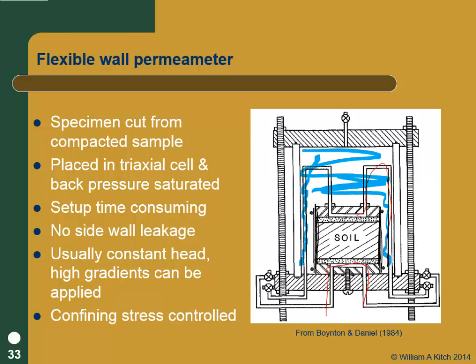And you eliminate the issues with falling head tests. I guess the only other one that's run, well, the compaction mold ones are still run quite a bit because they're easy to run. And you can put those on your triaxial panel too. You can run those at really high hydraulic gradients, and you can get flow rates for clay soils out of them pretty easily too.